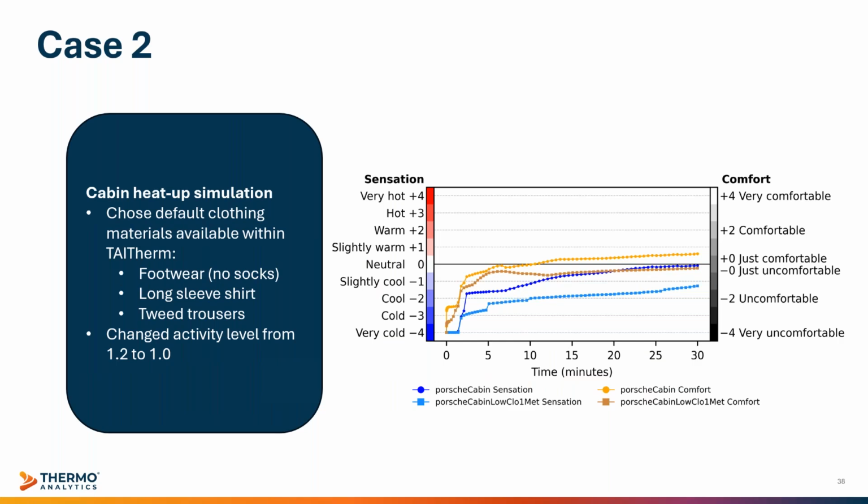It's important to be intentional when picking our boundary conditions, but it's also important to investigate the final results that maybe don't look as expected. So if I got these cold results shown in the light blue and the darker brown line, but I thought that the HVAC conditions that I chose should really result in my person getting warm within 30 minutes, it is worth investigating that to see if I set up my model in the proper way.